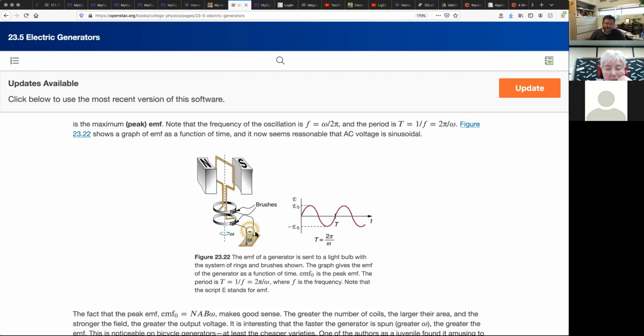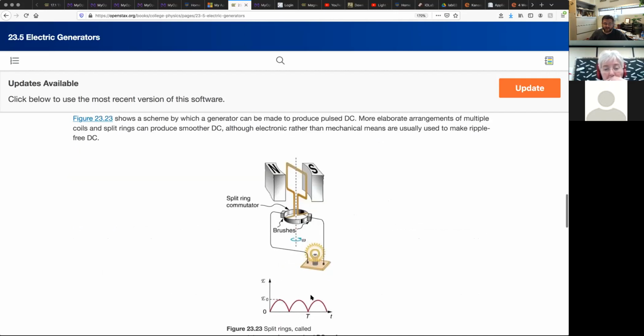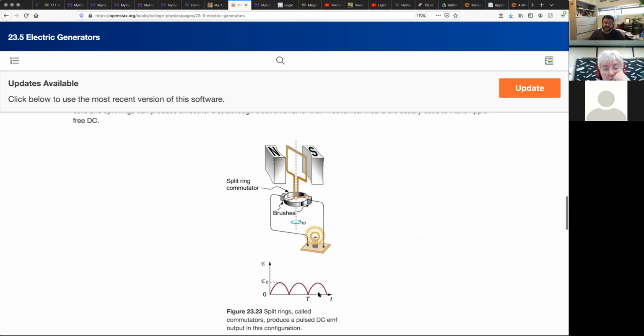If this is a light bulb that is made of an LED, just a regular old LED, some LEDs do not like the current to go both ways through them. So it would only light up maybe when it was up here, or maybe when it was down here. In this case, it's going to just blink on and off, kind of, it'll wobble a little bit in its brightness. If it's wobbling 60 times a second, you won't be able to see it because your eyes can't see something that fast. And also it doesn't cool down fast enough for it to really change its brightness.